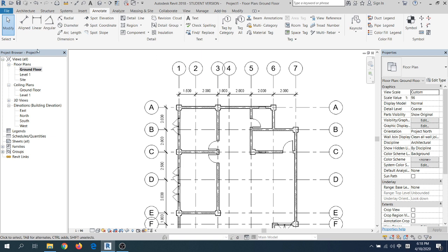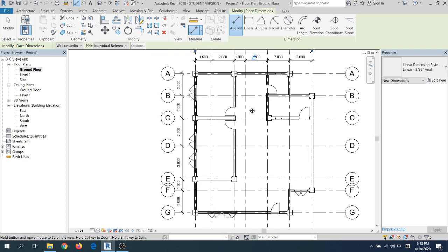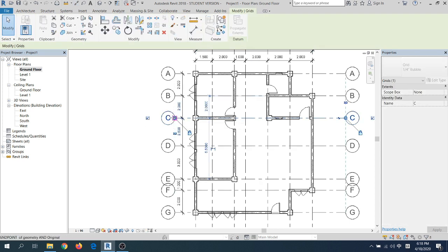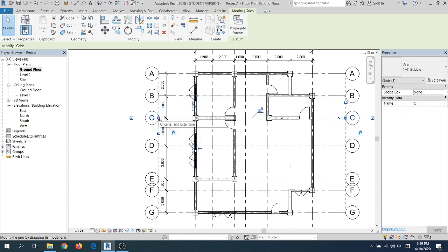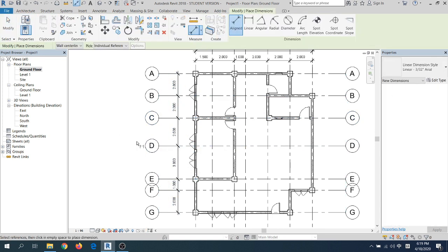design. Lastly, you can add extra annotation. For example, from line 1 to line 7, which is the total figure for this amount, and then which is 10.5 meter. Do the same thing for the left hand side of your annotation, which is actually click modify and slightly extend or prolong the A to G, and then click the line and move it down and add an annotation which is from A to G accordingly. So the total length is 12.5.